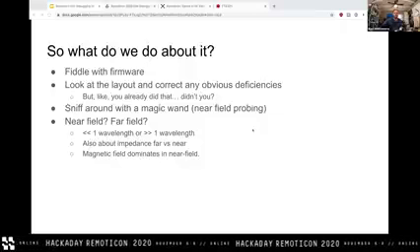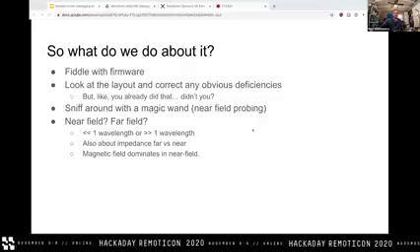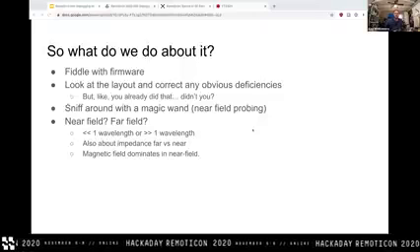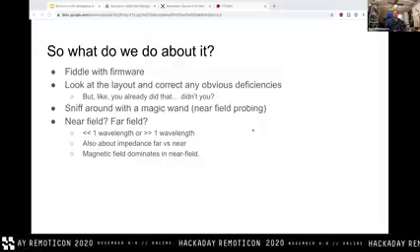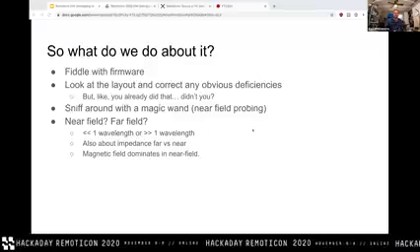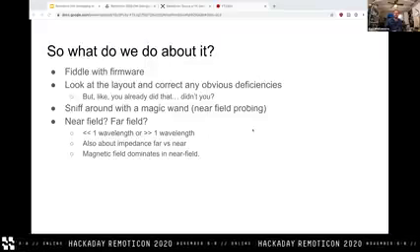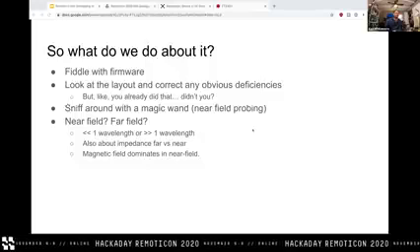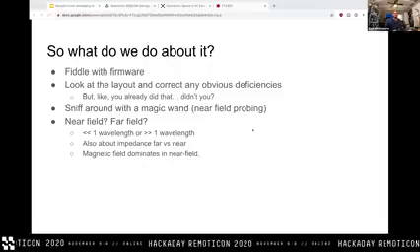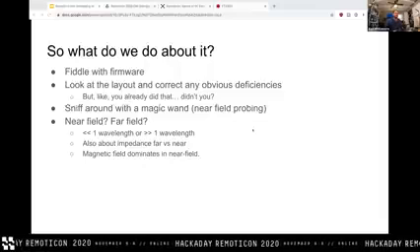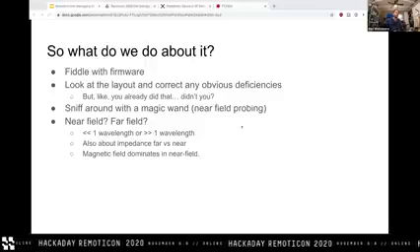And more to the point, you still have to have a point of A/B comparison. Plenty of testing houses will let you come in and do live debugging and measure your product while you're making physical changes and firmware changes and all the rest of it. But it's super expensive. Time in a test cell is not cheap. Metal walls cost money. So it's best to figure out what you can about how your device works and what might be causing the problem on a bench, before you get to that point.